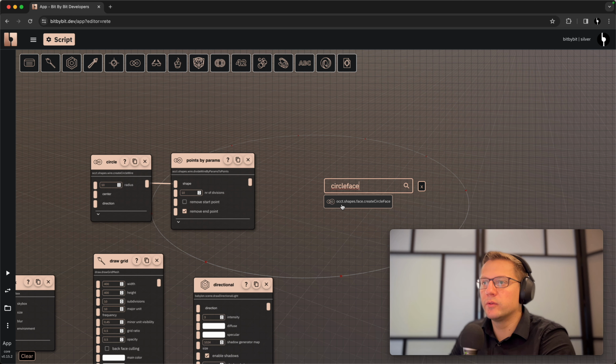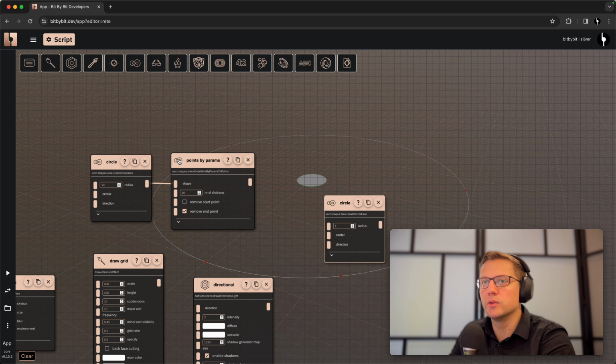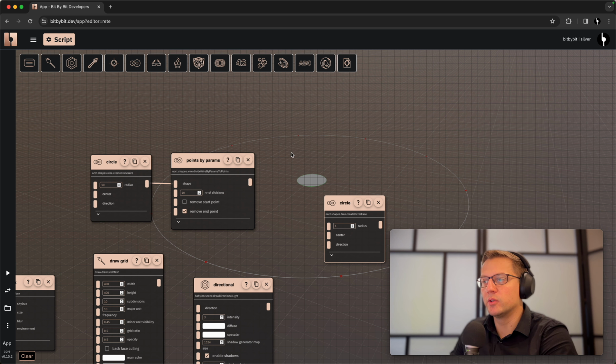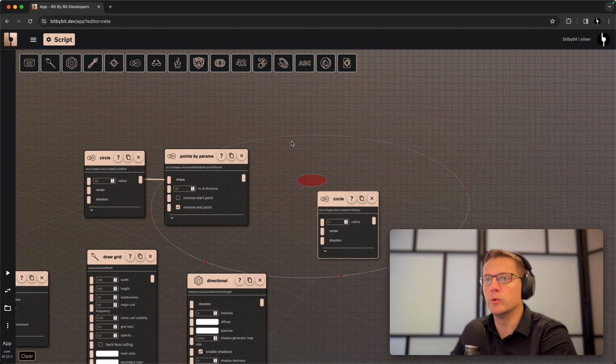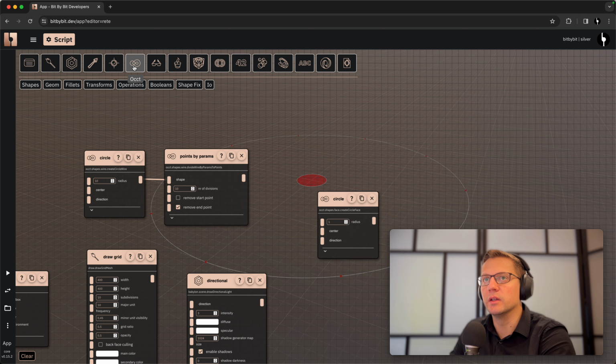And you also have to understand that we always use OpenCascade algorithms with other OpenCascade algorithms. There are ways how to go and transform the things from one kernel into another. But when we work with OpenCascade geometry, we usually tend to just work with these components that are coming from this category. So if you want to transform the circle, you will look for the transformations in here under OpenCascade kernel.